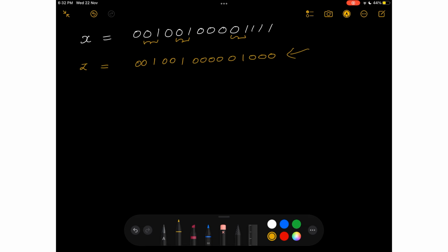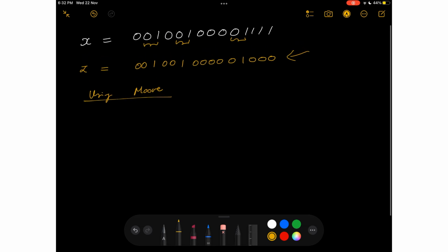First, we have to realize or know how many states we need to achieve this. So given that we are using Moore, we can say that we have a 2-bit number, so 0-1 is 2 bits. So it means we're going to have 3 states. So state 0 is when there's no 0 detected.